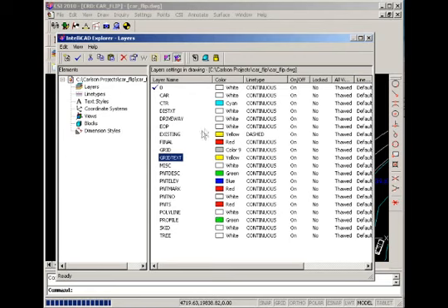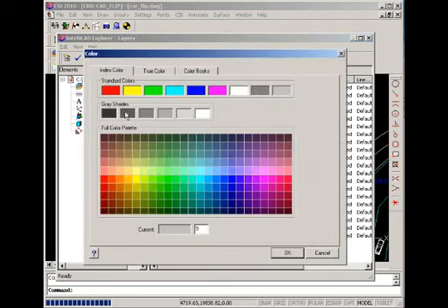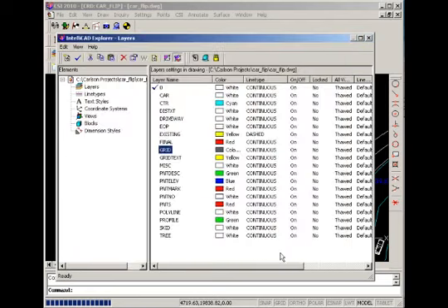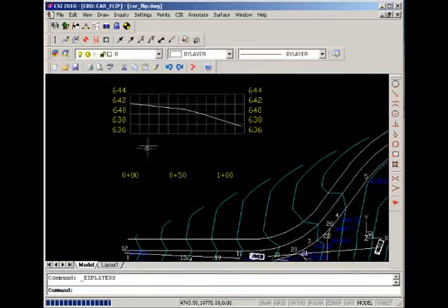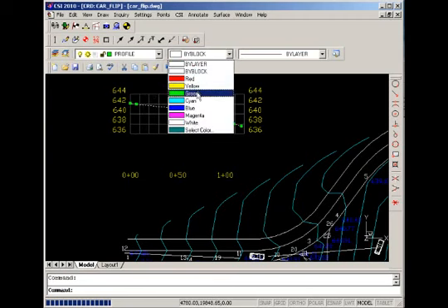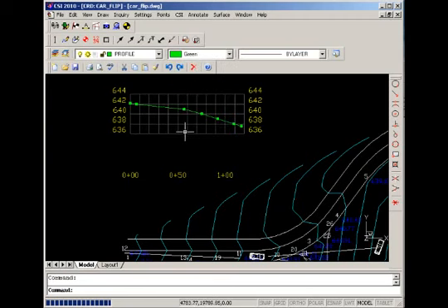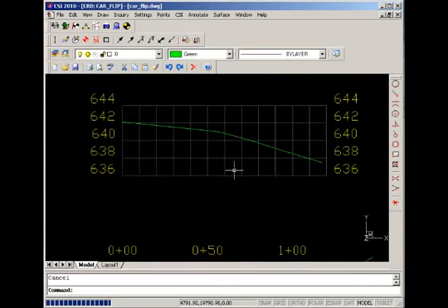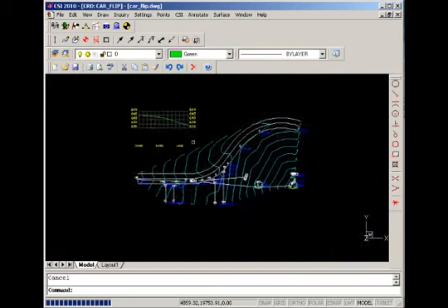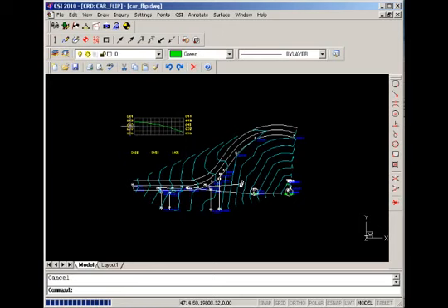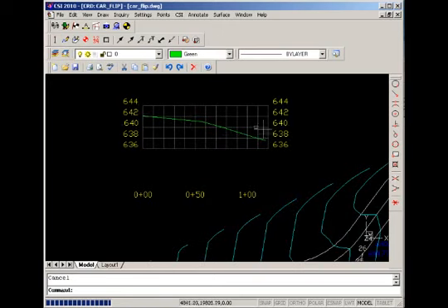And our grid. And we'll exit out. And we can also change the color of the profile. If we highlight an object, we can then come to the color control and set a color for it. This elevation change will be helpful for us when we get into the accident reconstruction tools when we're prompted for an elevation change.